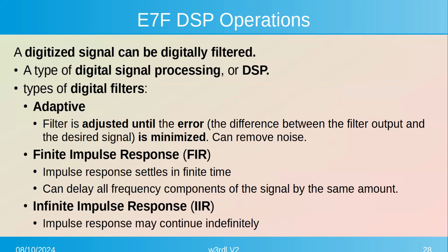In the case of adaptive, they have a reference signal that they want the output to look like. So they compare the signal coming in to that reference signal and adjust the filter characteristics, the coefficients, in order to produce an output that is maybe an amplitude multiplied, but of that same waveform, follows the wave shape.